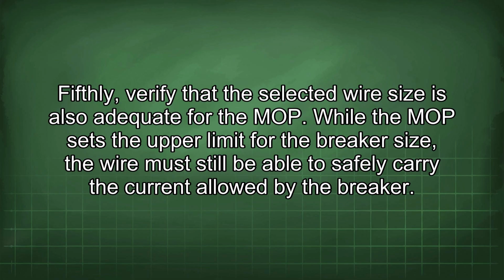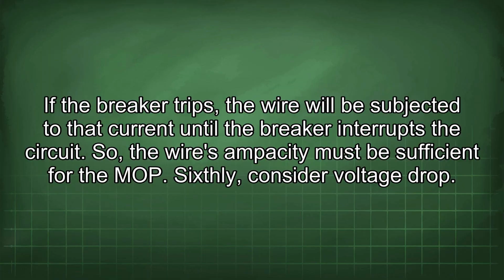Fifthly, verify that the selected wire size is also adequate for the MOP. While the MOP sets the upper limit for the breaker size, the wire must still be able to safely carry the current allowed by the breaker. If the breaker trips, the wire will be subjected to that current until the breaker interrupts the circuit. So, the wire's ampacity must be sufficient for the MOP.